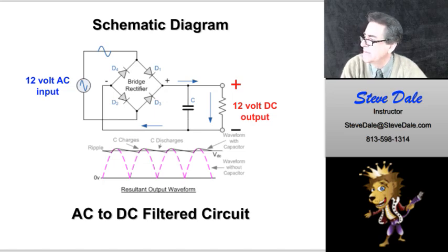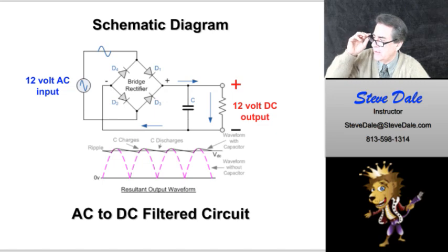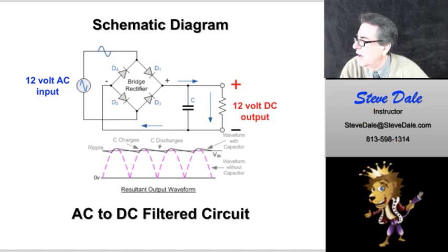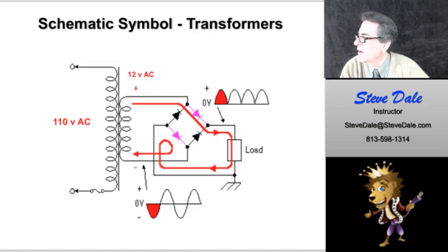So it goes through a series of diodes called a bridge rectifier, allowing the electrons to only flow in one direction. And then you can see you have a capacitor there that represents a capacitor with that little C by it, designating it's a capacitor. And that capacitor will charge up on the high side, and then on the low side it'll discharge, and it'll give you a smooth output of direct current, which you can use to charge batteries and run our switching systems. Okay.